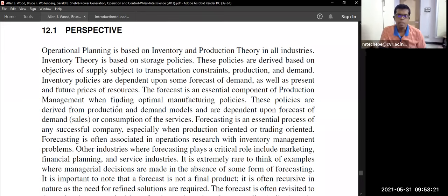Say for example January 31st. What is the load? By seeing that forecasting data, that is the load duration curve, we can easily find out in which hours the load is maximum, so that we know approximately how much to generate. We can't predict very accurately, because no one in this world can predict the load demand accurately. So it may change.